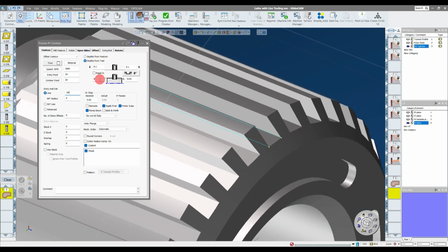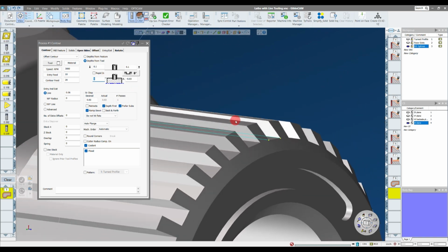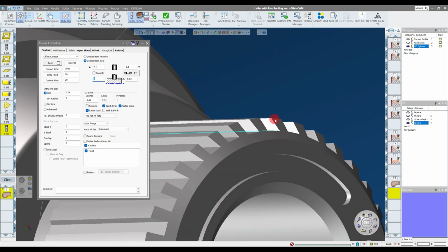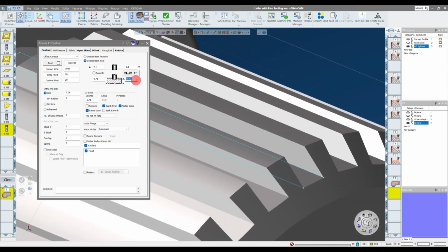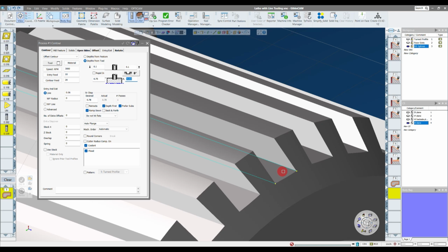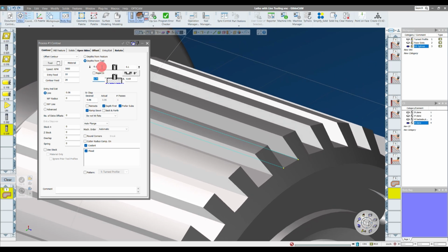Now, this is where you really need to be careful. The reason I always start in this lower left corner is because this tells me where I'm going to start machining. And I'm going to start machining at this outer diameter, which I know is 0.75. And because it's 0.75, I can interrogate for my depth. And this is going to be the bottom of my cut, which I can either interrogate the geometry or this flat here. Now, the reason I start in this bottom left is because if you look right above it, your approach is still set to 0.1 from when we were machining on the face of the part. And this would be a crash.